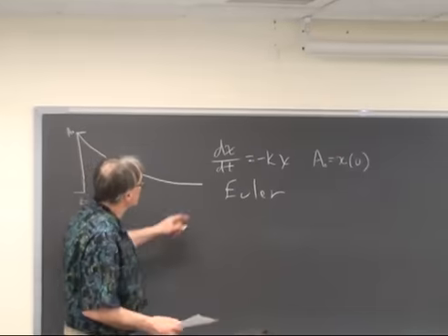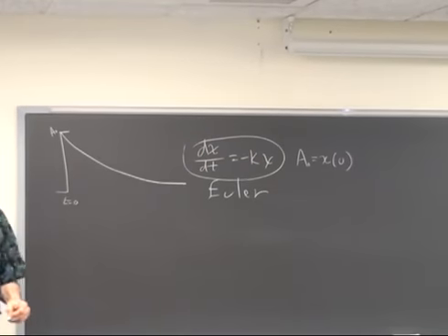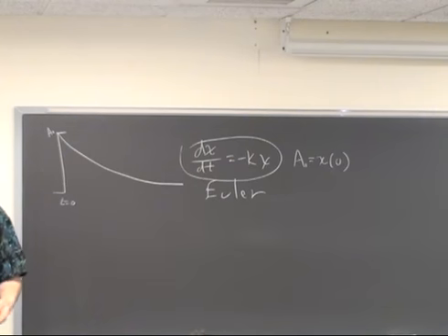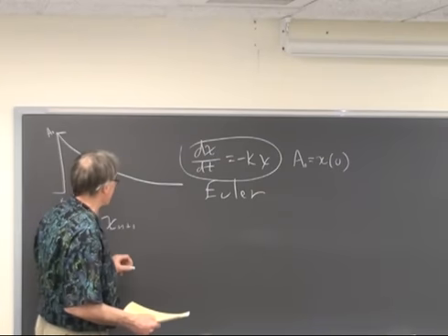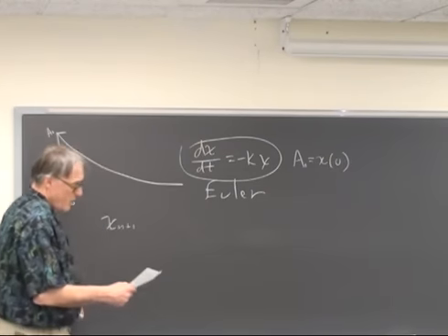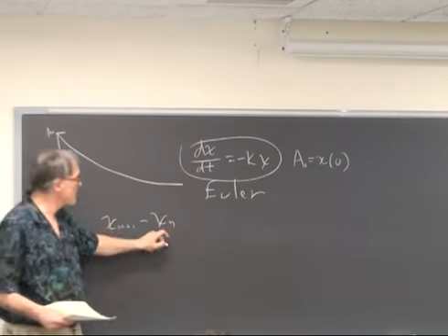All right, so we can rewrite this. If we want to solve this on a computer, we need to turn continuous time into discrete time. The discrete time being the sample frequency that we're going to be synthesizing at. And we're going to rewrite this differential equation with an index, x_n, n being a time index.